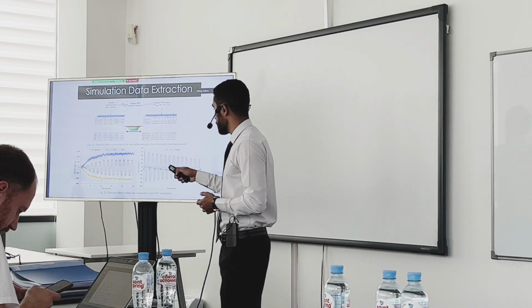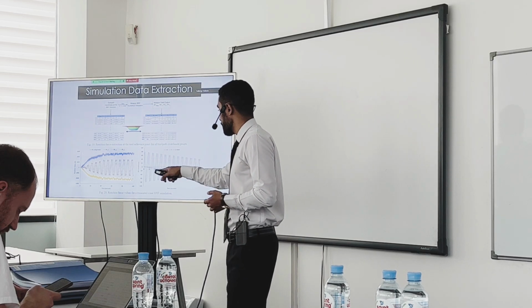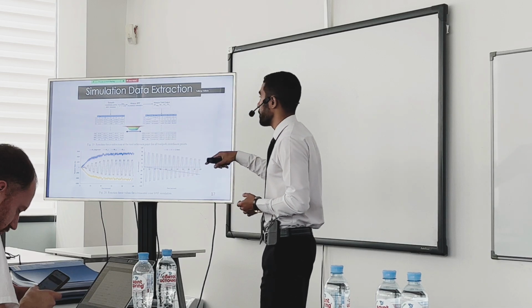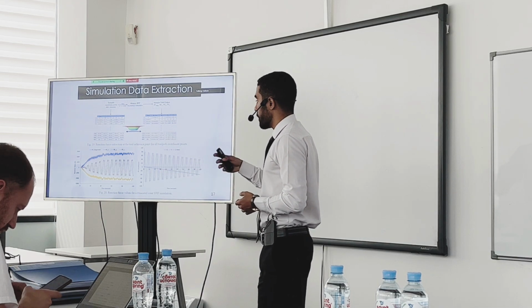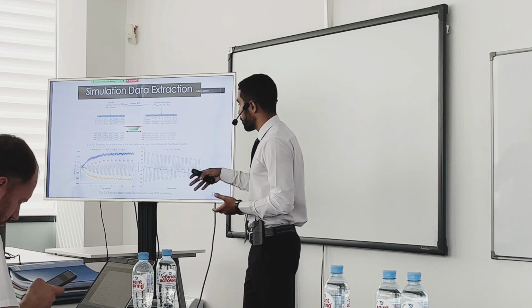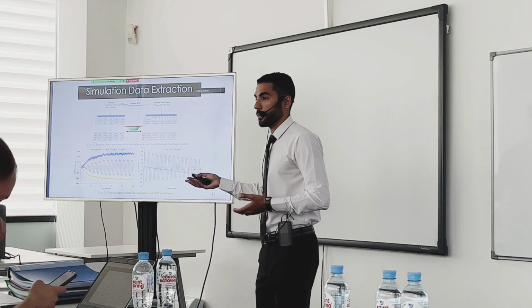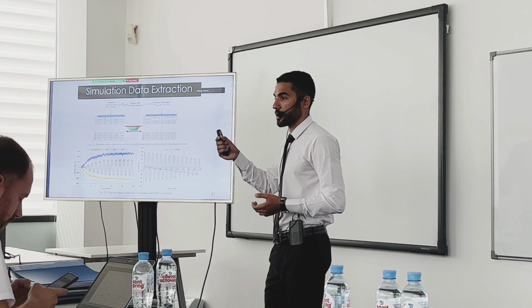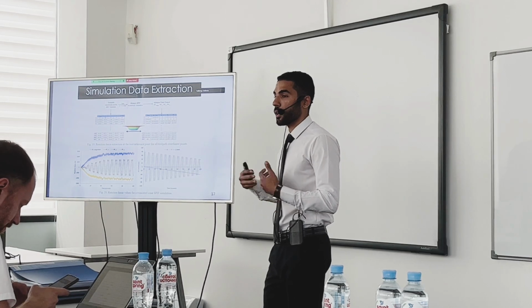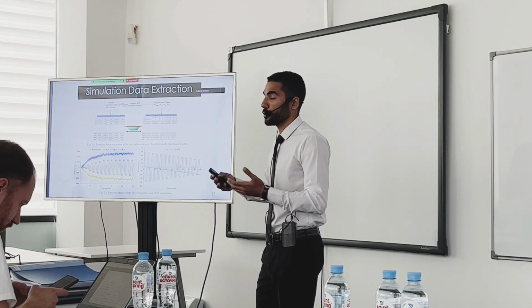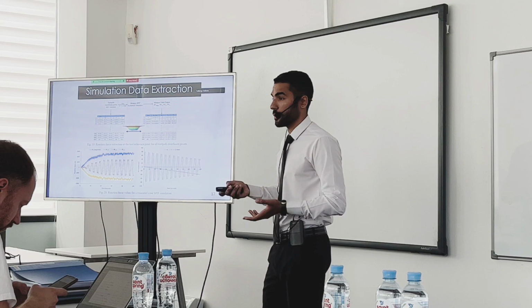It's worth mentioning that in Figure 19, the magnitude of the forces increases over time, and this is normal behavior because the sheet thickness becomes less, which requires you to apply more force in order to deform the sheet further.